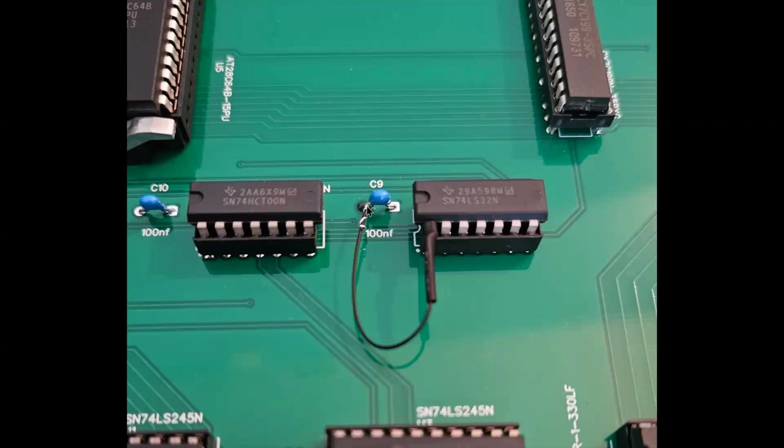here to this bypass cap that we have here because we had a good ground point right here. So that's the way I chose to do that fix. And again, if I did want to undo this for some reason, I always could. I could unwrap that pin and bend the pin back down and reinsert the chip and snip that wire. So I felt that was a better way to go, and I was more comfortable doing that than the other.